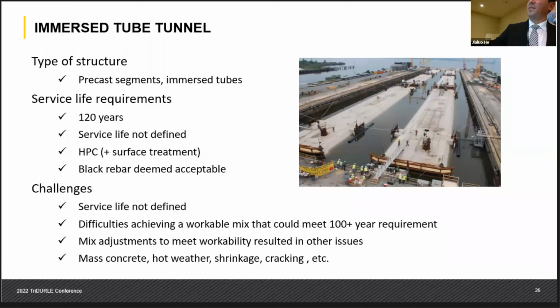Okay, so there were a lot of different issues with that, and obviously with mass concrete because there were larger portions, so we needed to put in cooling pipes. All of that, obviously, we were able to manage. But we spent almost over a year defining the right mitigation strategies, trying things, doing trial after trial to get the right solutions. So it takes more time, right?